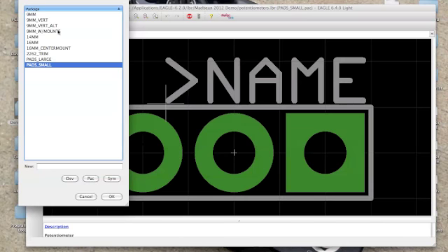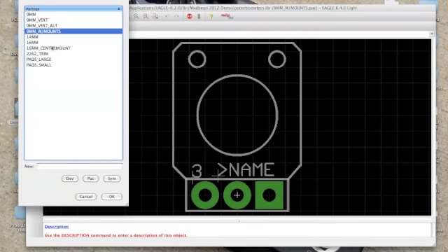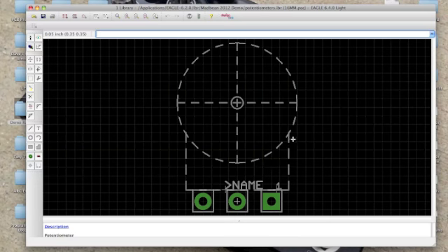If we had an issue with one of these, for example, I can already tell you that this potentiometer image has an issue. One of the things that we know from actual parts themselves is that a PCB mount pot is 5/8 of an inch from the center of the second lug to the center of the pot shaft.